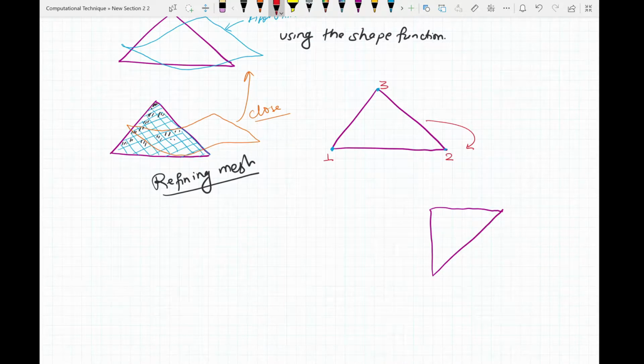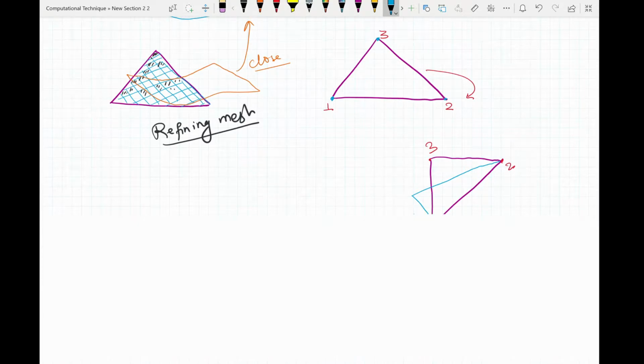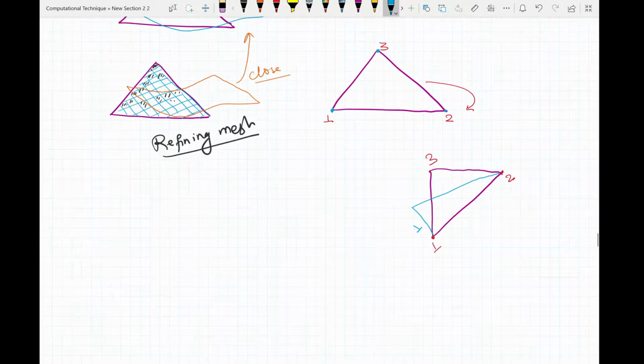As we know, each node will have its shape functions. Now here, as per the definition of your shape function, if you are looking at node 1, then its value must be 1 at n1 and 0 at all the other nodes. Now when you plot this, you get a linear line. This is similar to what you looked at in the bar element.